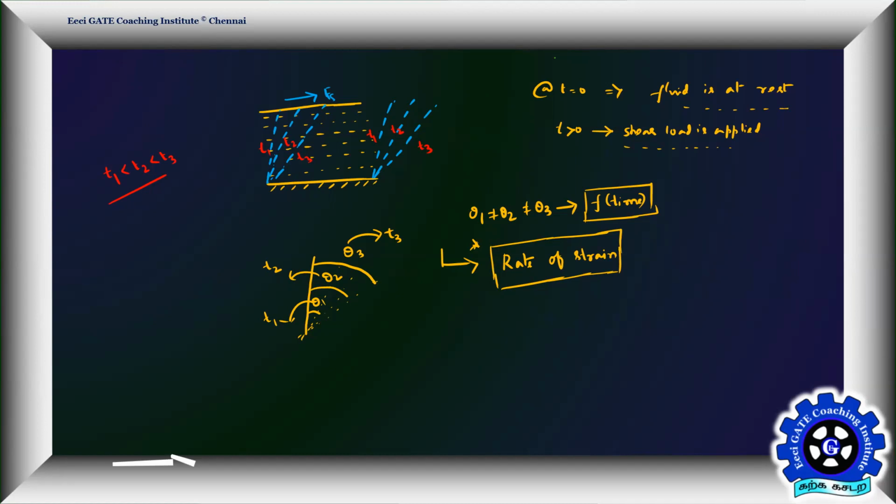That is from our common sense. Like any object in your home, you apply some load, it will not break or deform. It has some particular load after which it starts to deform. That is what a solid body is about. Whereas in fluid mechanics, it doesn't matter. Any small load, it starts to deform, continuously deforms. So that's why you should talk here not about strain as you see in solid mechanics. You should specify with a term called rate of strain. Rate of strain, very important.